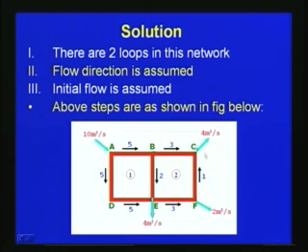Now we will apply Hardy-Cross to see that we get the correct value. These are only assumed values. So now we will proceed with the iterative procedure which we have discussed earlier, and step by step we will do the calculations here by using the Hardy-Cross method. This is shown in this table.